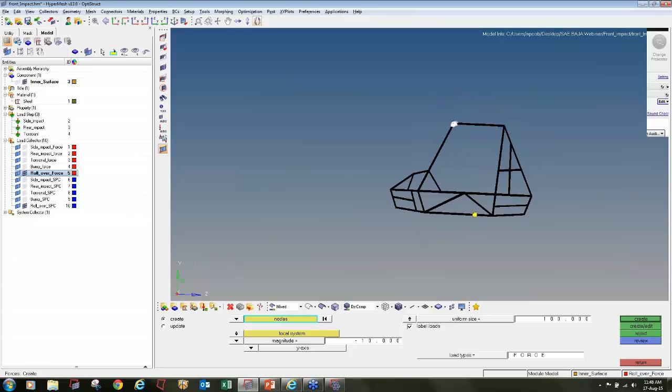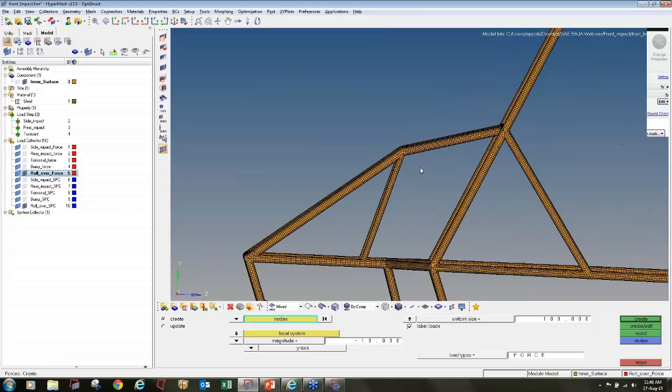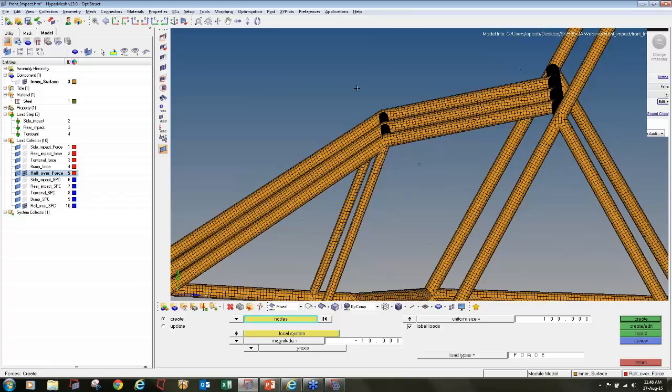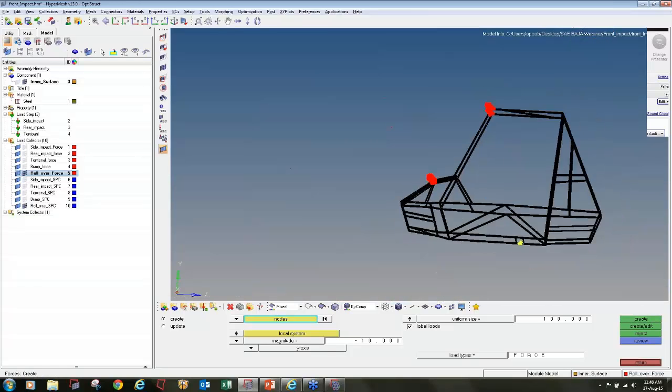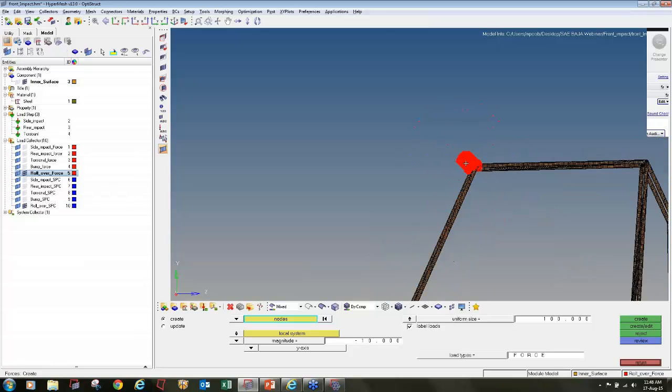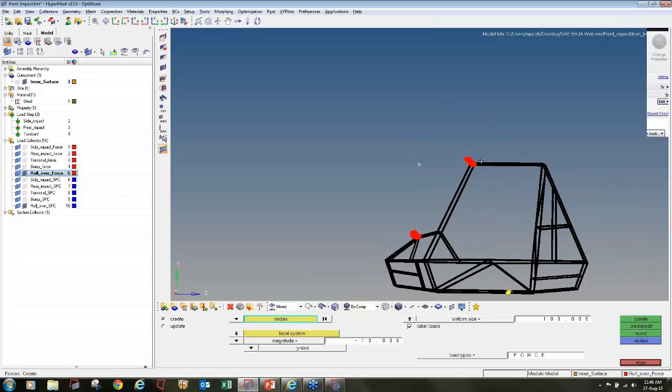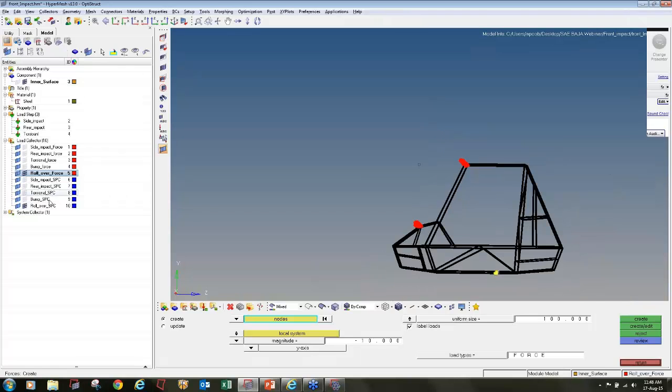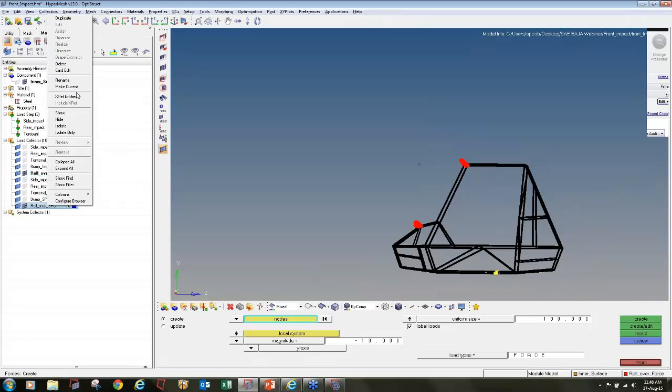So first point of contact, this, or maybe this one. So I will click on create. Now you can see I have an angular force. My force is angular now. That's what I want. So I will make the SPC current.